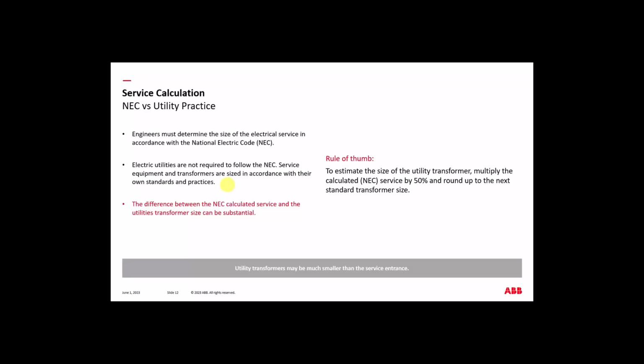Done. Because they have a lot of data from basically all the customers that are on their system, so they've got a really good idea of what the real demand is going to be on the buildings. So they usually do that. That's how they do their takeoffs, the watts per square foot method. There's some other ways they do it, but generally it's based on the type of occupancy, their tables of watts per square foot, and then motors.